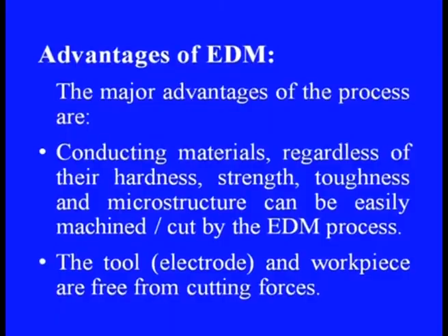Now, let us have a look at the advantages of this electric discharge machining process. The major advantages are: this is useful for conducting materials regardless of their hardness, strength, toughness and microstructure. This is what I have indicated at the very beginning.